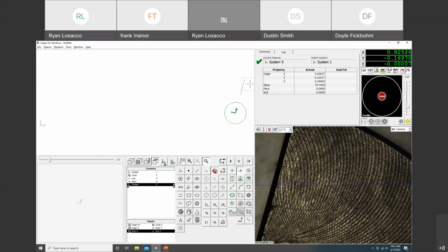And then now when we hit the PCS view, my part's straight, how my blueprint probably looks, but we can see that that's my stage square. So my part's crooked, but since we set our system and our skew to that, we're good to go.